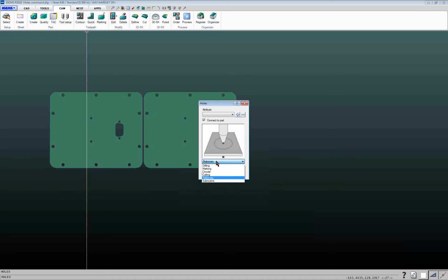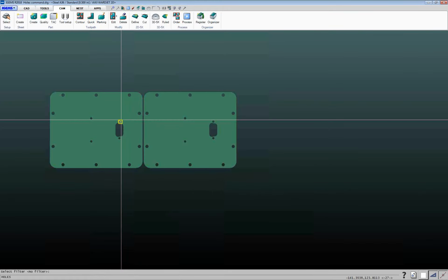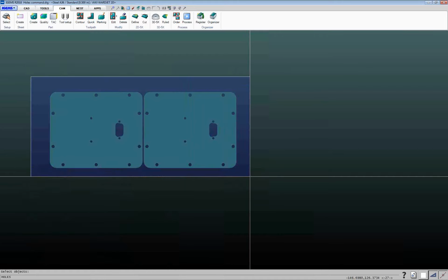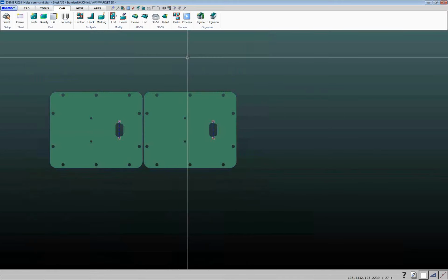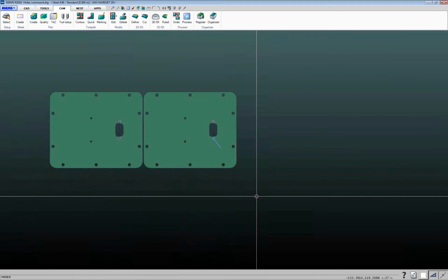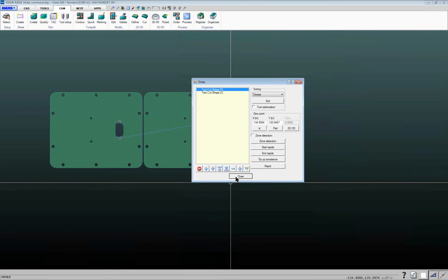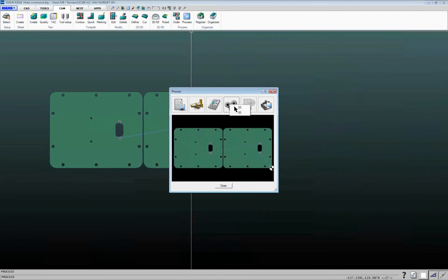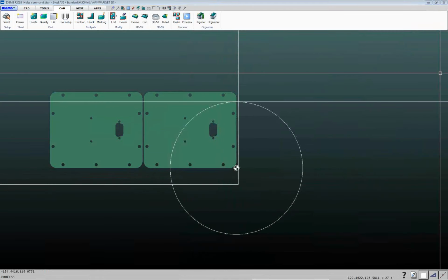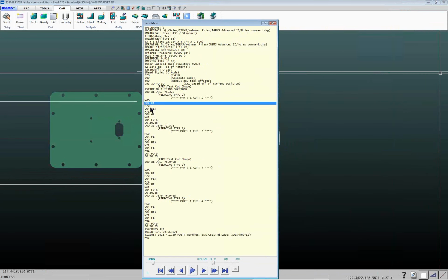Stationary would be similar to the marking one in that it would just do a stationary pierce at that location. So if you wanted to actually pierce through versus just making a light mark, if you use the stationary option, it'll use whatever number is in the material file for the delay at that point. So in this case here, comes over, turns our water and abrasive on, sits there for 15 seconds, and then turns the water and the abrasive off. So that one there, you'd pierce all the way through, with the idea of using that as a point to locate off of with the drill off the machine later.